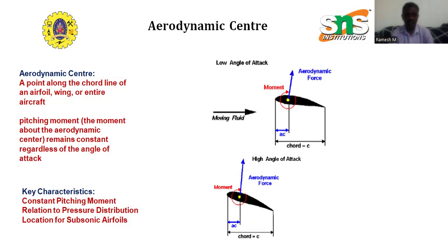The center of pressure: first, what is center of pressure? Actually, center of pressure is the point where the total aerodynamic force acts. It's like a center of gravity. The aerodynamic force means lift and drag we have to concentrate. Unlike the aerodynamic center, the center of pressure moves with changes in the angle of attack. So aerodynamic center does not change with respect to the angle of attack, but the center of pressure changes with respect to the angle of attack changes.